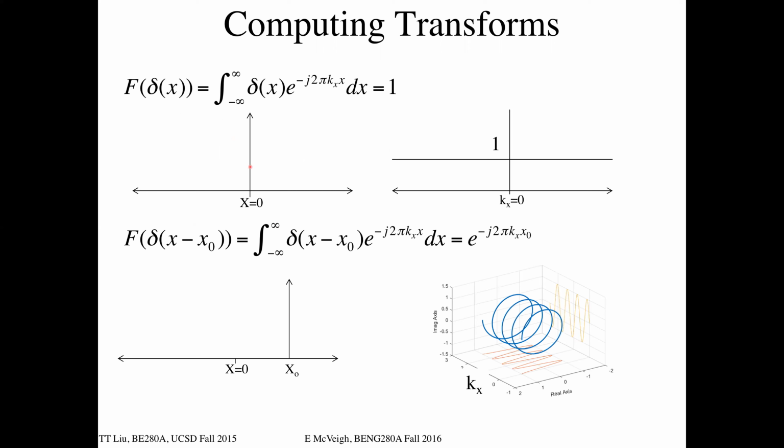So here's a diagram. Here's our super sharp function that has a lot of high frequencies. And then in the Fourier transform, it's saying, oh yeah, I've got a lot of high frequencies, in fact all the way out to infinity, right? I need to add the same amount of power into that signal to build that function. This is like, if you're listening to the radio, and there's a static charge release or something, you get a pop, right? Like a bang. There's one amplitude that happens really fast and goes away, right?